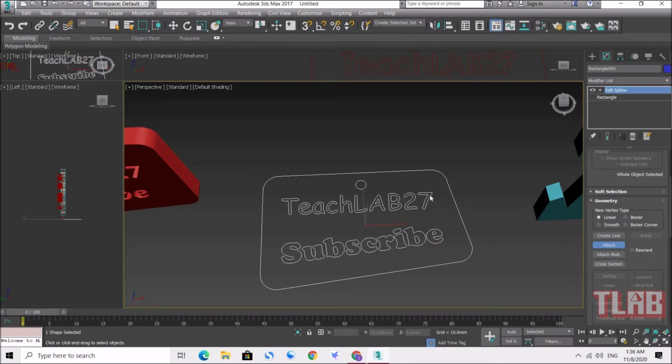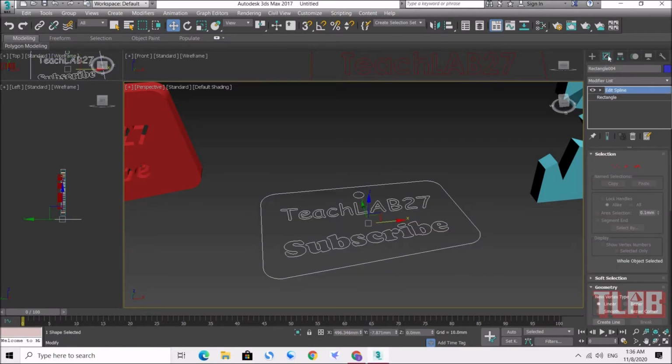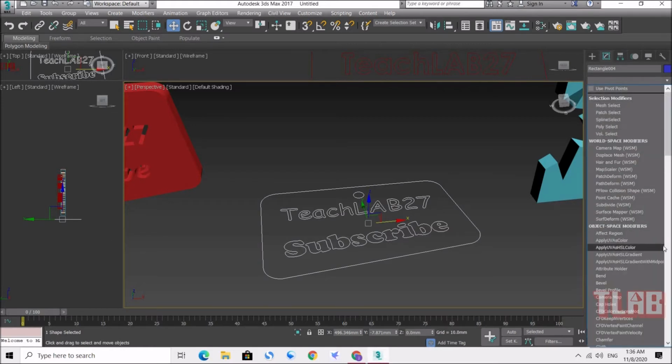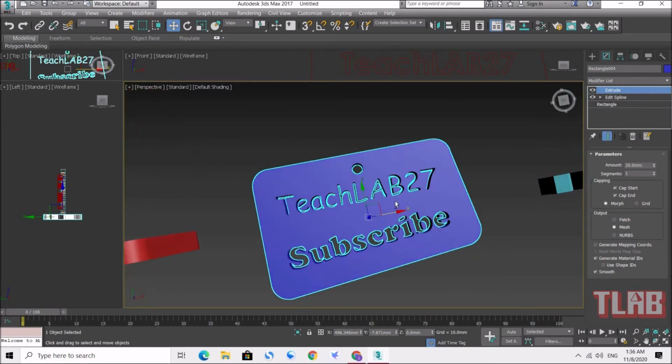Must select the whole. Okay. After that, turn attach off. Then now deselect. You can see the color is the same, all blue. That means they are combined into one object already. So now if you select it, you can go to the modify list, open, and now you can give S group. So now you can see.